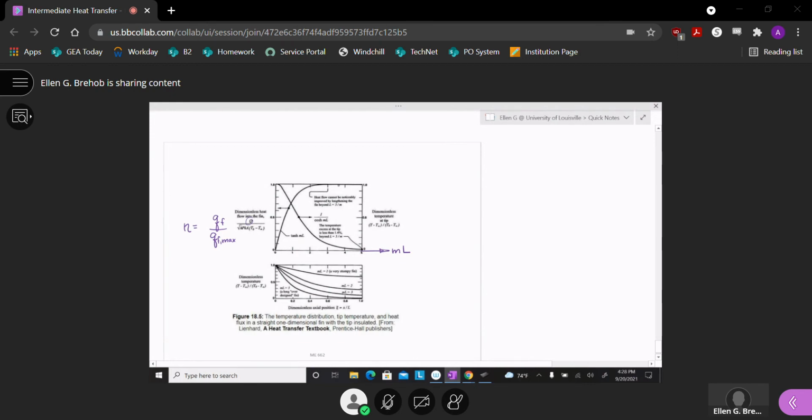And we saw the other day that that function is bound by 1 and -1, and we really only care about the positive portion of it. Okay? And it shows that by about the time we get to ML of 3, a combination of these features of the fin and the length of the fin, we get to about the highest fin efficiency we can get, about 1.